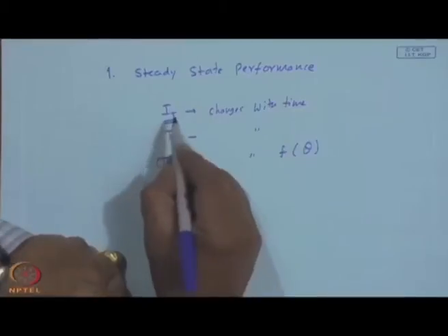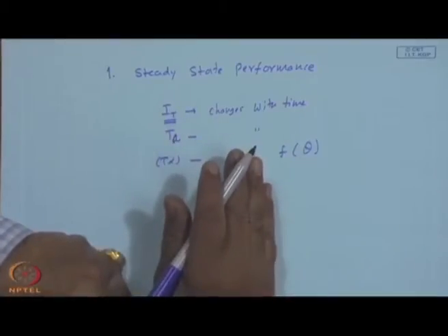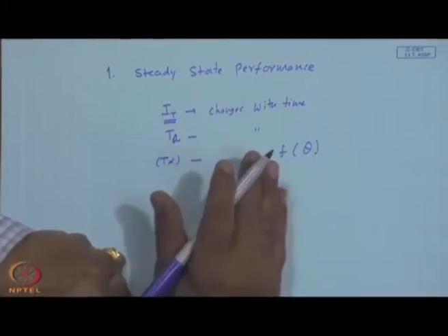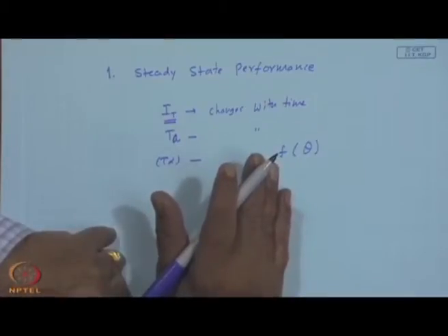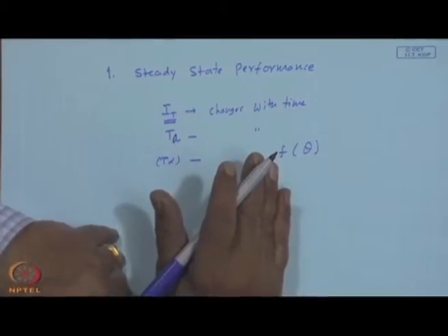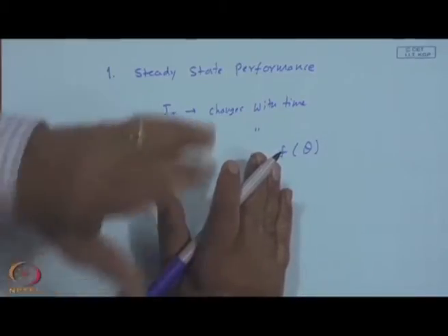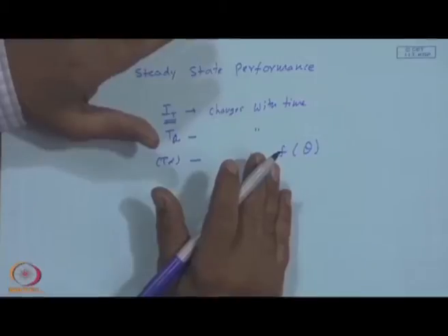In other words, we are trying to obtain what shall be the useful energy gain if a certain intensity of solar radiation, or on a short term scale I t, remains fixed. So, there had been sufficient warm up period and the collector has reached steady state, and if everything else continues to be so, what will be the useful energy gain?